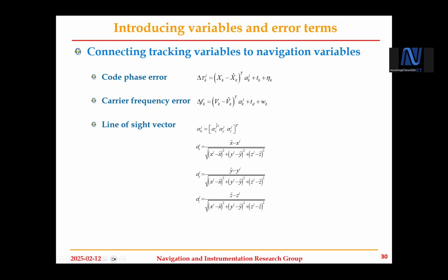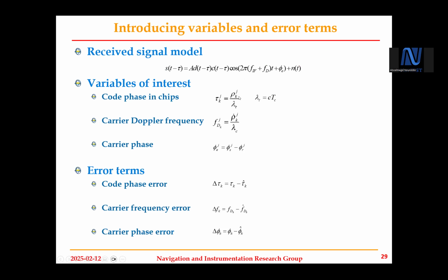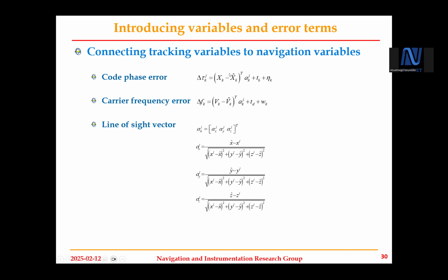You will see here also how this is connected to the position I mentioned earlier, because if we subtract the position, the actual and the estimated, that's indeed the error in the code itself, right? So instead of the range, the error in the position could reflect into the delay. That's how we implement those vector tracking loops. Same thing, the velocity of the receiver, the actual minus the estimated, reflects on the frequency of the receiver.